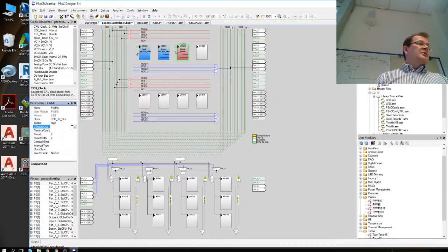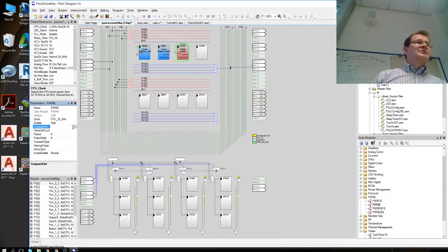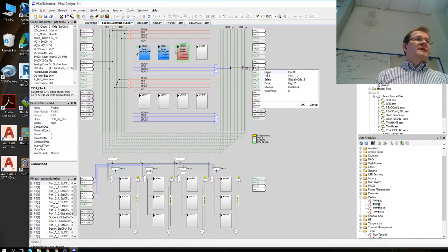Compare out. Okay, now we use compare out. It must be routed to your output pin. Okay, the output pin was 1.2. That can be connected on this. This is 1.2. It's an odd port. Port 1 is odd.